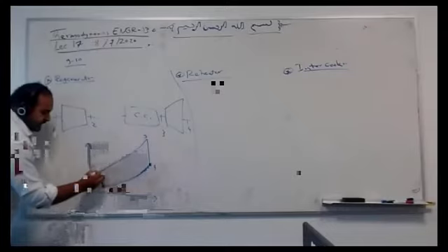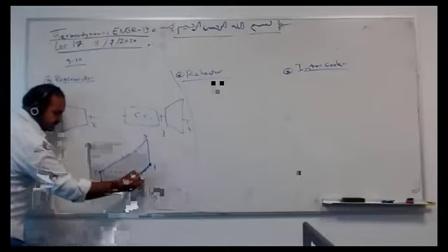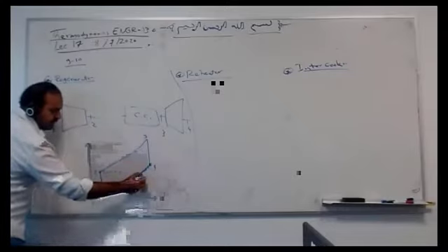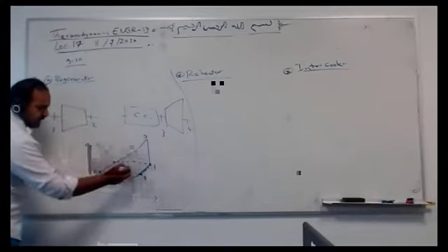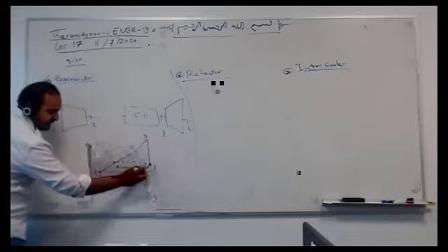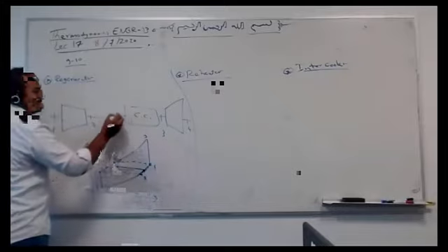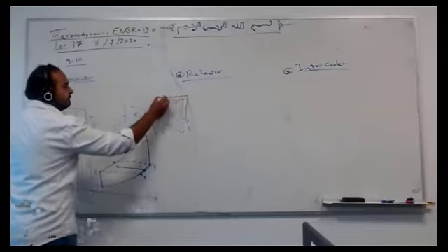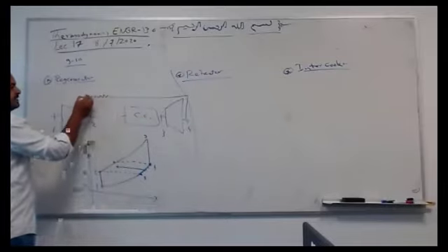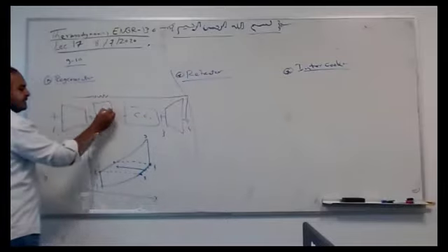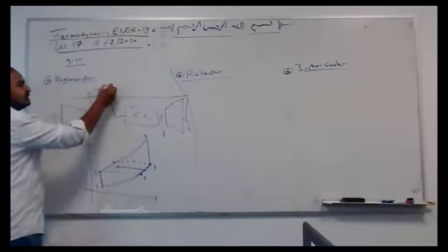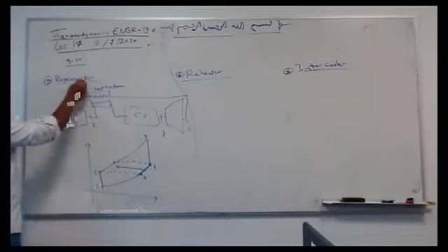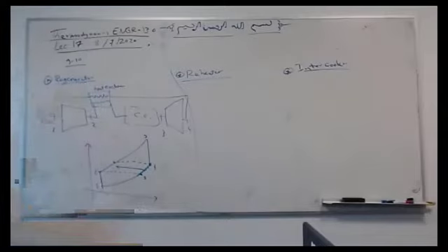Somebody smart said, okay, how about this? If I get this point, let's say 4, let's say 5. I take this heat, make it horizontal and give it to this part. So it will get some heat from here using a heat exchanger and pass it along. This is called a heat exchanger. Regeneration. Regeneration. So let's see the numbers.